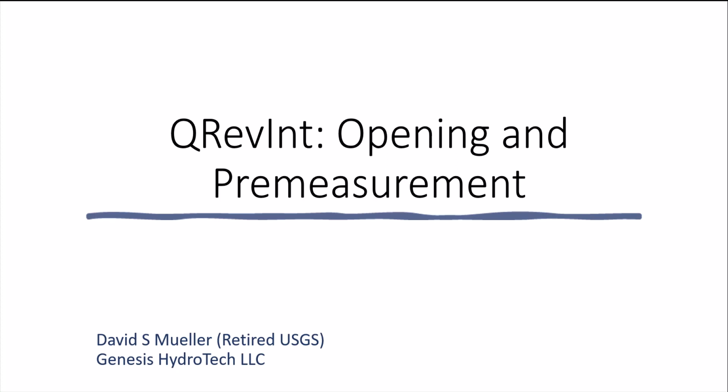In this session, I'm going to describe how to prepare and open TRDI and SonTek ADCP measurements in QRevInt and discuss the system test, Compass PR, Temp Sal, and moving bed test tabs and the associated automated quality analysis and user interface that you can use to make appropriate changes.